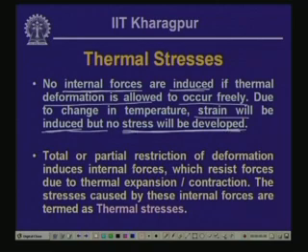Now, total or partial restriction of deformation induces internal forces. If this particular body is free to move due to change in the temperature, fine. But supposing I hold this body from two sides and do not allow it to move, since it will try to expand, it will exert pressure on this support, and as a result the body will be subjected to some internal forces, and thereby there will be stresses induced in the body.